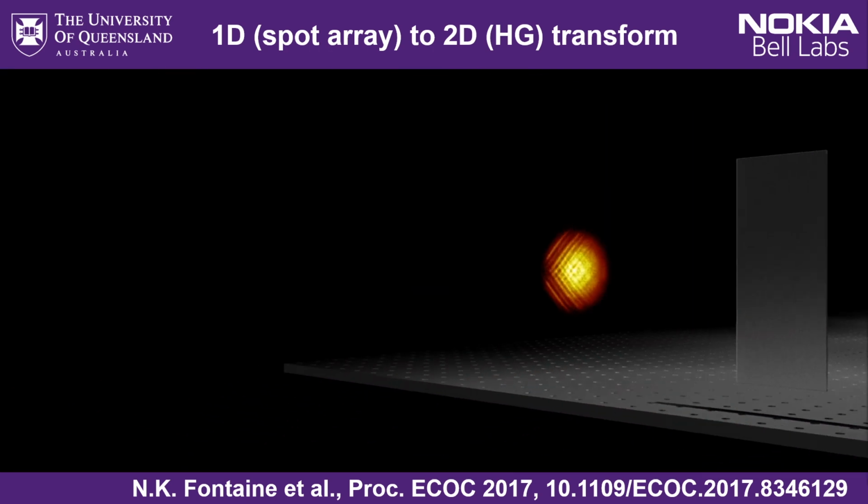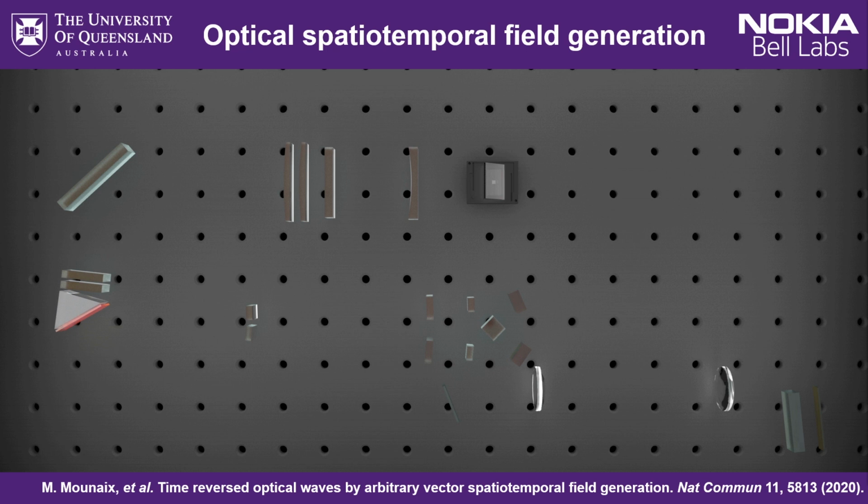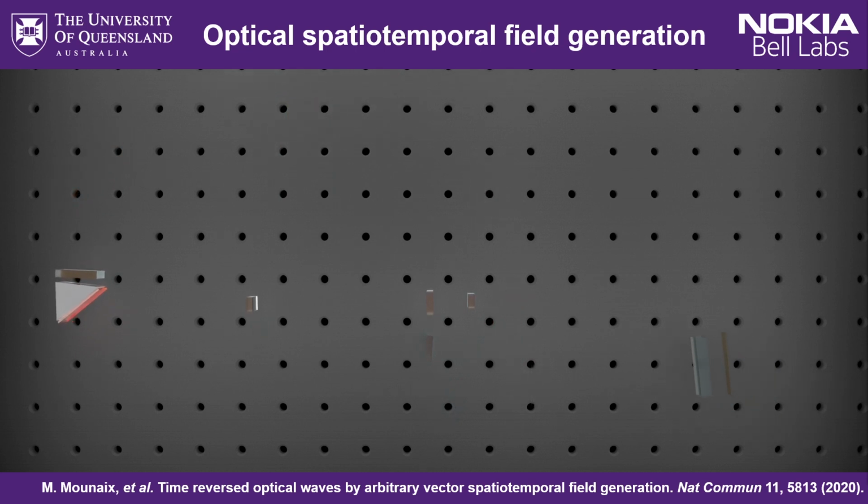So through the optics of the system, the SLM will be carved up like so, allowing the 2 spatial dimensions, one temporal/spectral dimension, as well as the polarization dimension, to all be controlled using that single phase mask on a flat 2D surface. Let's have a look at how such a device works. First, I'll simplify that diagram a bit and get rid of some of the polarization optics, mirrors, and other stuff that you do need in practice but isn't really that important conceptually.